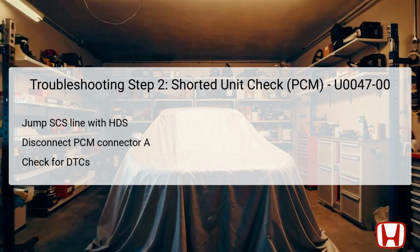In this step, the focus shifts to checking if the powertrain control module (PCM) is shorted, which could be impacting CAN communication, leading to DTC U0047-00. Start by ensuring the vehicle ignition is in the off position before proceeding. Utilize the HDS diagnostic tool to jump the SCS service check switch line, maintaining this mode for over 1 minute to allow for adequate monitoring of the system's response.